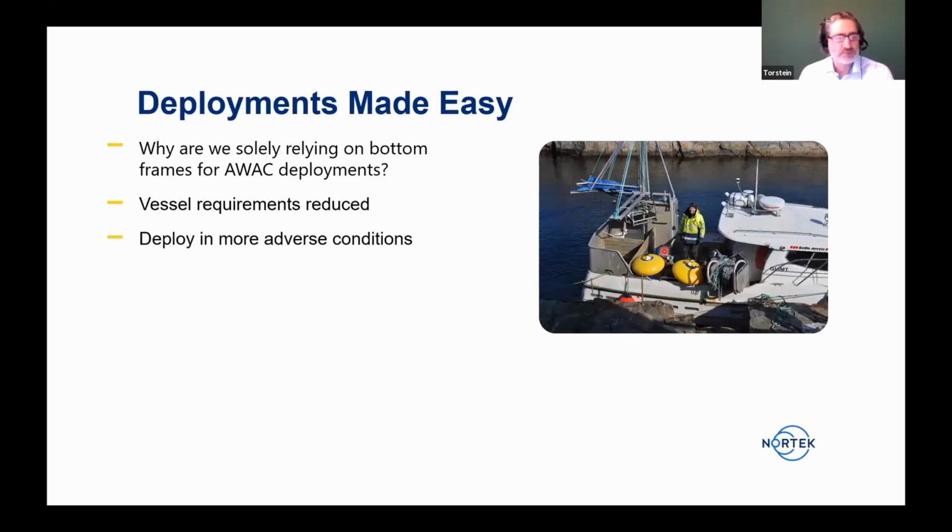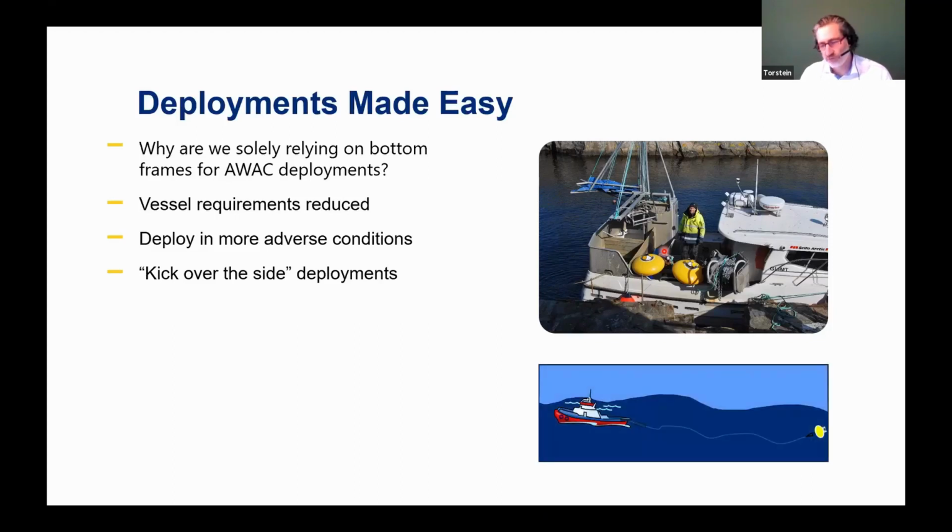And we can deploy in much more adverse conditions because you don't have to settle the frame on the bottom. And it really became a kick over the side deployment. So this is how we would do it. We'd stream the buoy off the back of the boat, keep the weight on the boat, and then when we got on location, the site, we'd kick this weight over the side, and it would suck the buoy down to our location that we wanted to measure from.